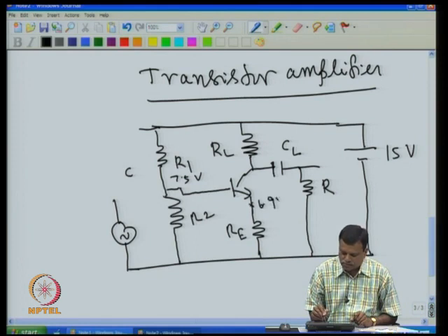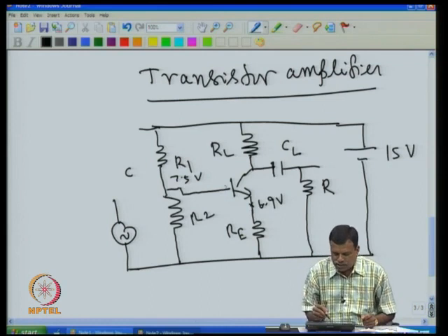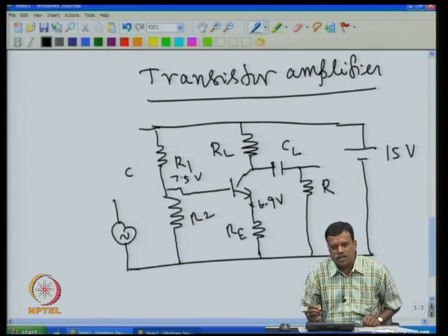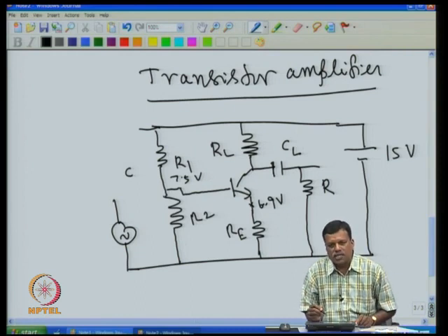6.9 volt. This is because we know that for any appreciable conduction, we need a base emitter voltage difference of 0.6, and this is a very important assumption that we have to remember, and we will be using this in very many places. The base emitter voltage difference in the forward bias condition will always be around 0.6 if the transistor is in a useful working range.